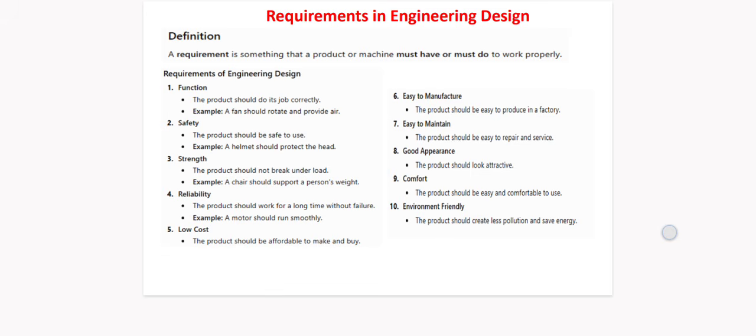First, we need to know what quantity of water it should pump, what pressure is required, what is the operating speed, what is the power available, what type of fluid will be handled, what is the expected service life, what are the size and weight limitations, and what is the allowable cost. All those are called design requirements.